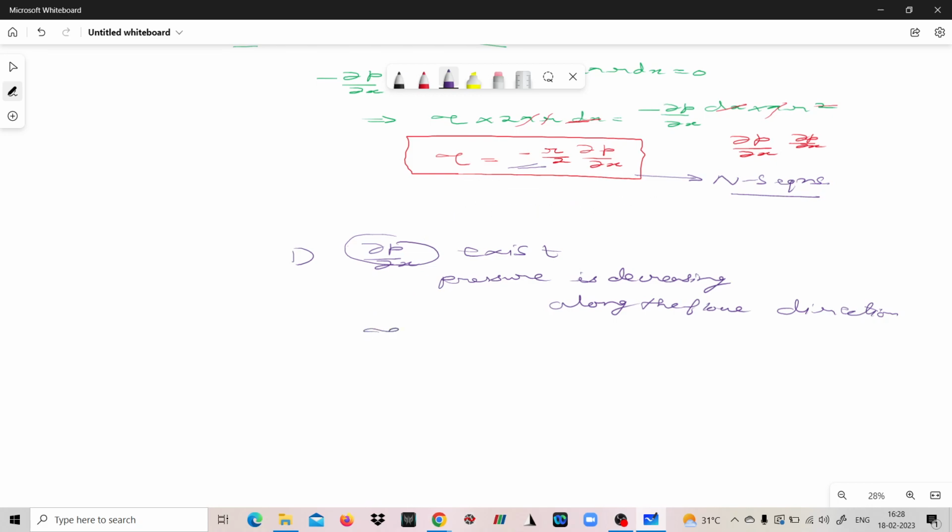So, if you look carefully, this equation is similar to the form tau is equal to minus m x, where x is nothing but r. What does this indicate? It indicates that shear stress varies linearly with r.